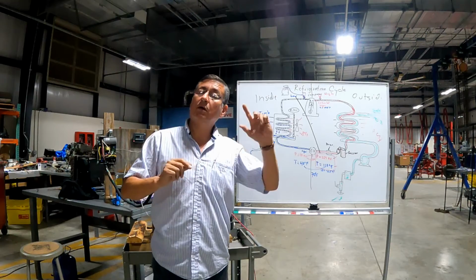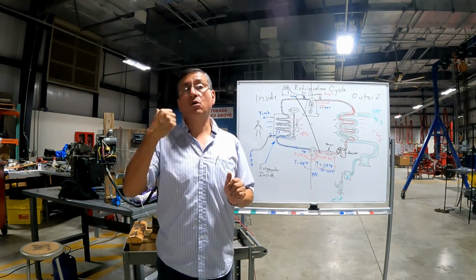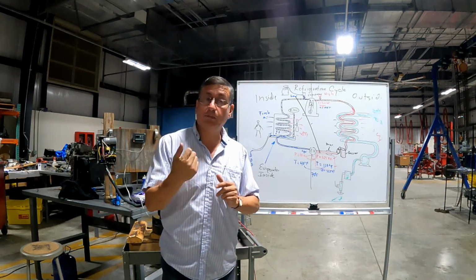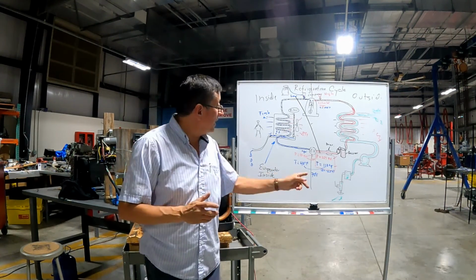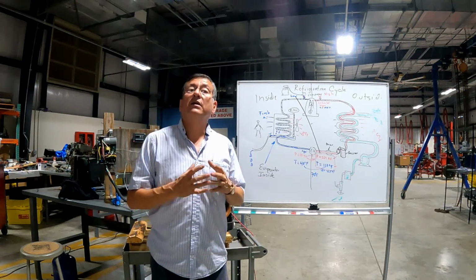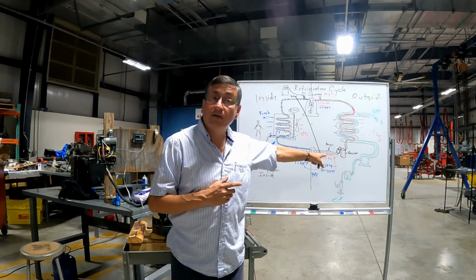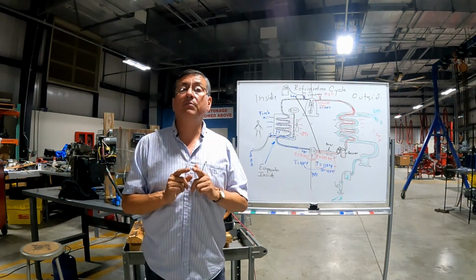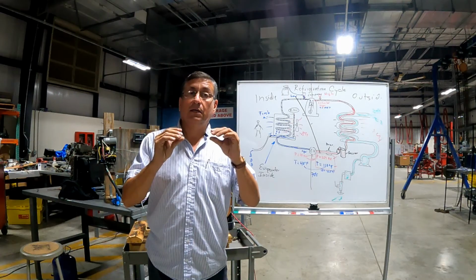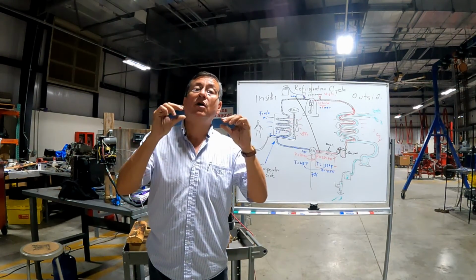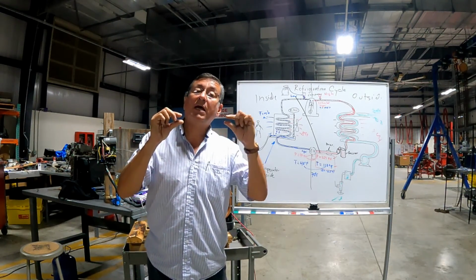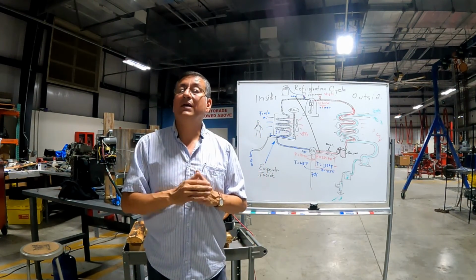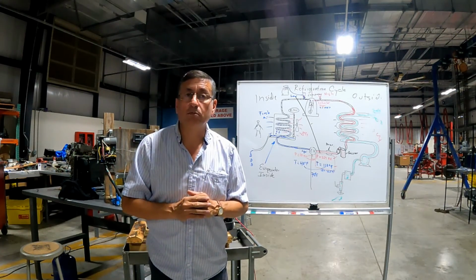We have two coils, outdoor coil and indoor coil. We have the compressor, and the other vital element that we explained before is the expansion valve. The expansion valve receives the refrigerant liquid from the receiver at high pressure and high temperature. Internally the diameter of the pipe decreases between the input and the output, and of course the pressure decreases dramatically, and the temperature.